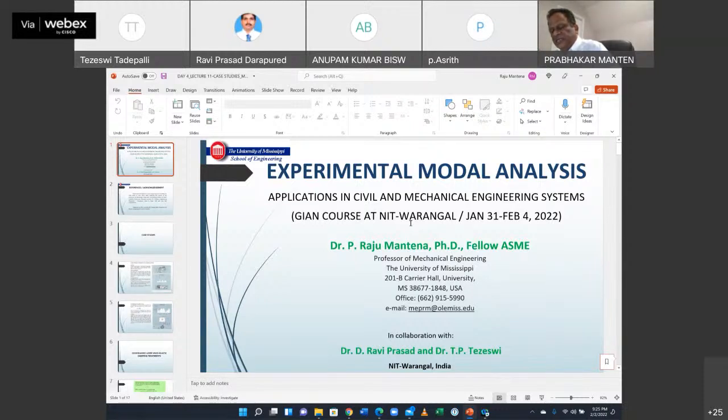At some point of the original resonance, the whole energy is moved onto the smaller mass in this system, and they start opposing each other's movement. Most textbooks cover this. Daniel Inman's textbook, which I use for my class, shows you the mathematical part of it for the tuned absorber.